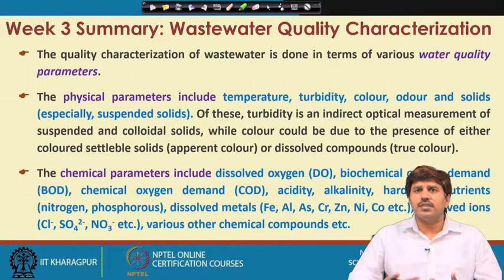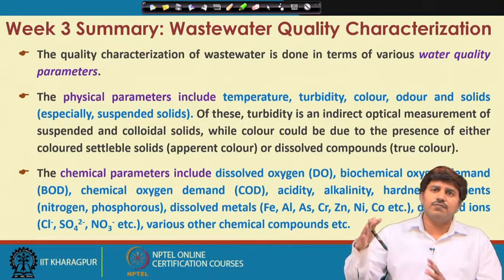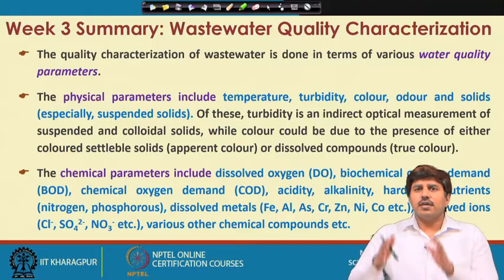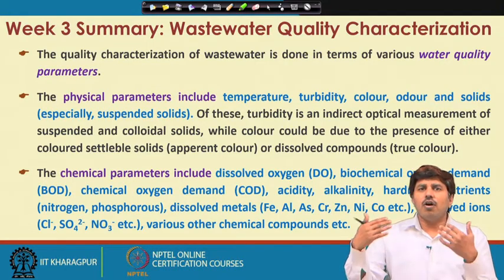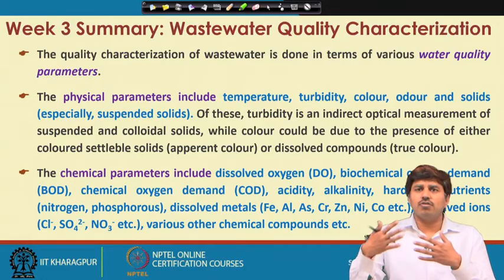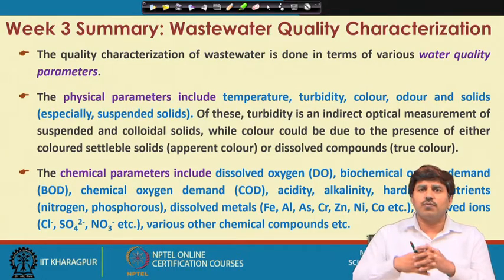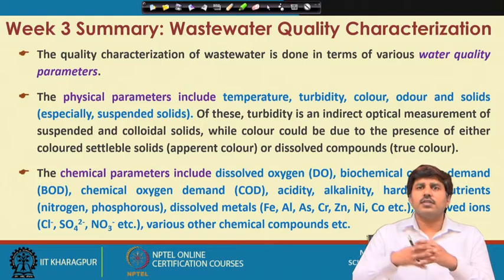Apparent color is caused by the settleable solids, which can be removed if we just allow the water to stand in a static condition, so that those color-causing substances get settled. Or it could be true color, which is due to the dissolved compounds, which cannot be removed without proper processing. Just settling cannot remove the true color.